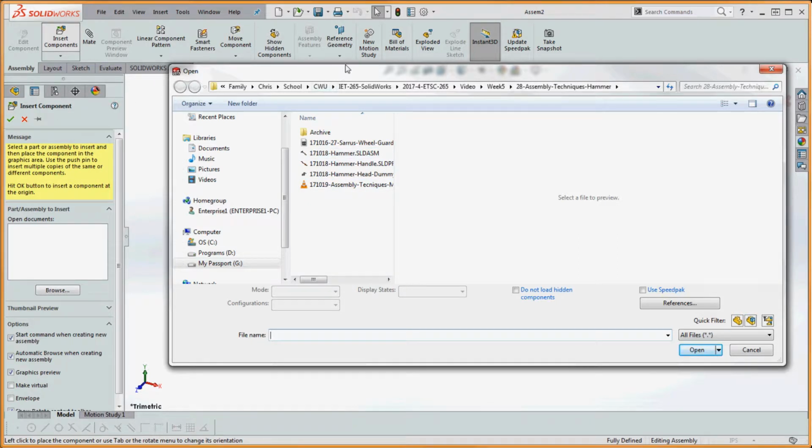So this is a dialog box we saw from the very beginning. And when you open up an assembly file from the very beginning, it will usually kick into the folder that you were in last or some similar folder. It's going to suggest a couple different parts. So we can select it here too, or you can go up here to the pull-down menu, go to Insert, and then go through the options in there too.